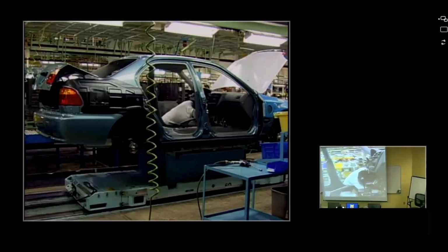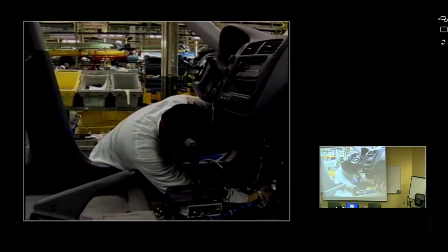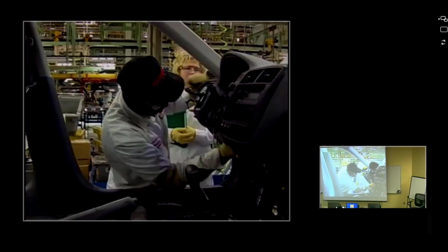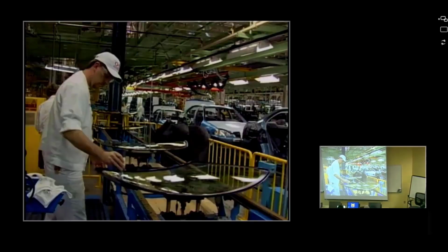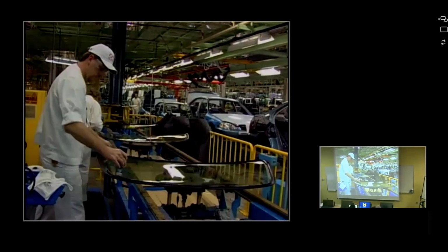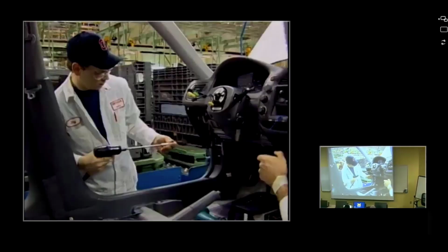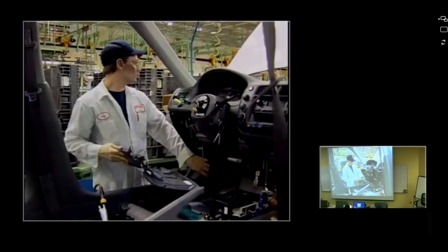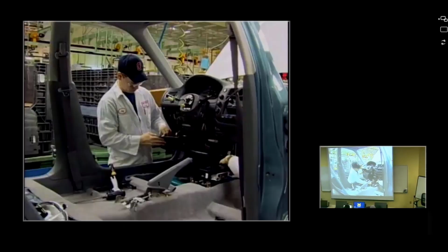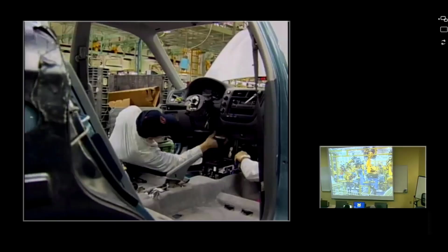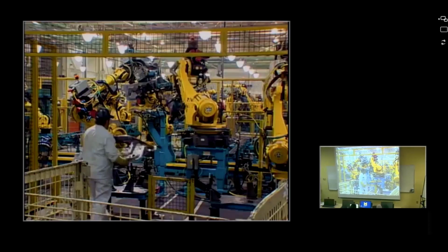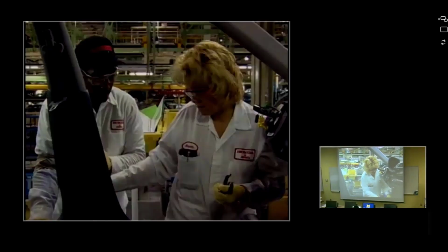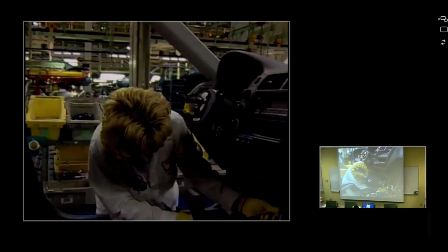In traditional assembly lines, workers complete the same task over and over. At Honda, workers are trained in a variety of tasks. They rotate workstations regularly to avoid fatigue and to maintain quality. Because each station is designed for a specific task, there is little need for flexible equipment. Workers interact with tools more than in a continuous process, but much of the work, such as welding, is performed through automation. Still, there's enough flexibility at each workstation to offer a variety of options on the model being produced.